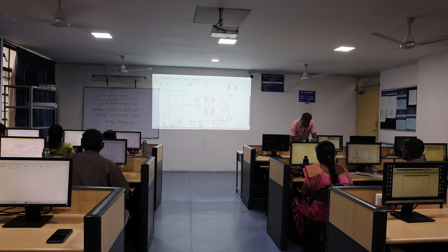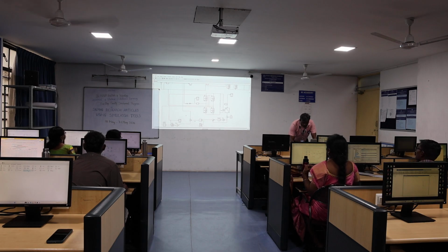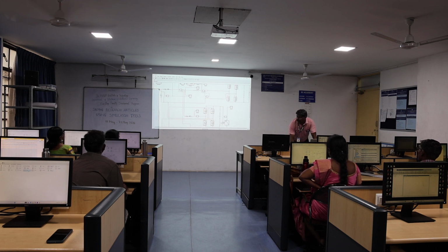Okay, please pay attention here. Here we need to compensate our source current. So we need to take a source current feedback. So source current is connected to the output after multiplication, that is after the multiplier, that is a reference current. This is the measured current. This measured current is connected to the supply side current measurement block. This is the source current.